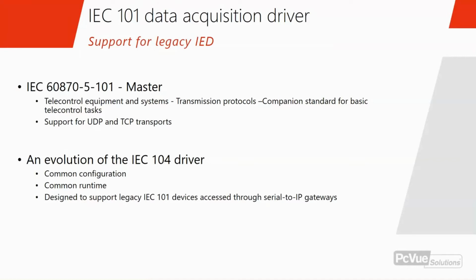But it's very important to note that in PcVue, we developed the IEC 101 to be used not as a serial driver, but as an IP driver using a gateway to address serial IEC 101 devices.